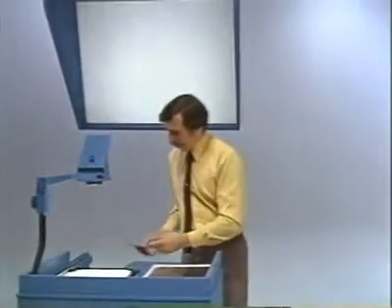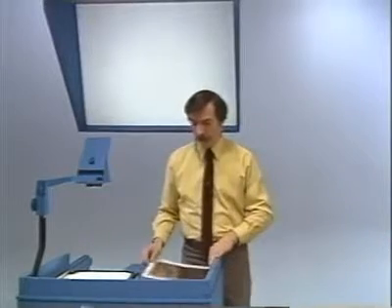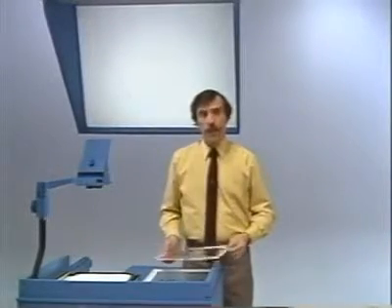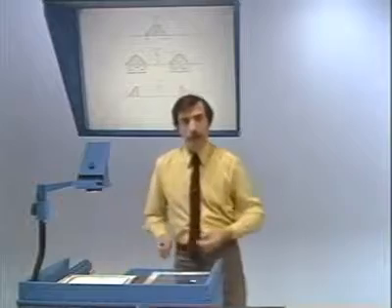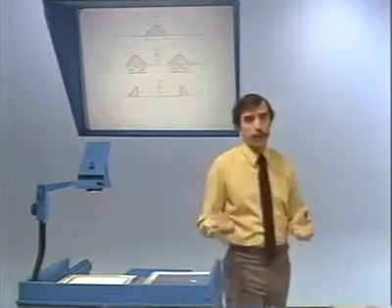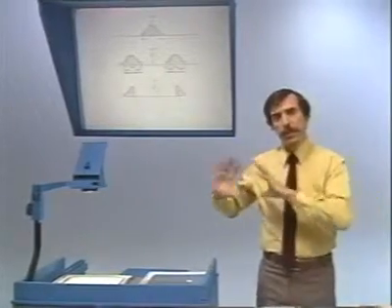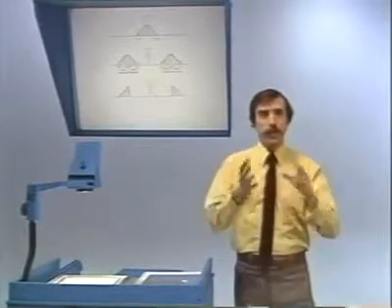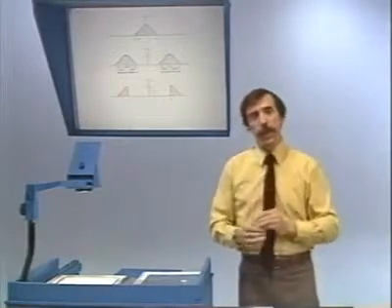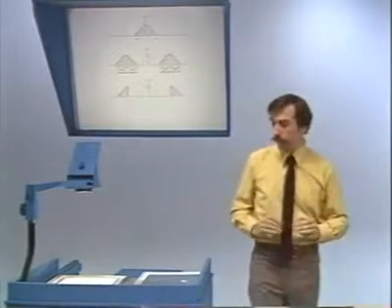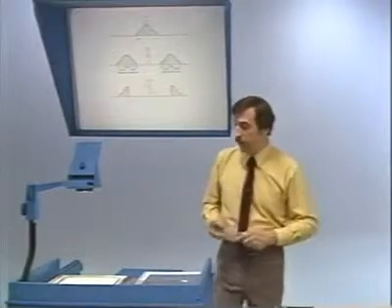Now, in the asynchronous system, as we've indicated, there's one source of inefficiency, which is this injection of the carrier. There also is a somewhat different issue related to inefficiency in sinusoidal amplitude modulation, and it's separate from the issue of synchronous versus asynchronous systems. In other words, it's not associated with the injection of the carrier. It's a very different issue. Let me indicate what that is.